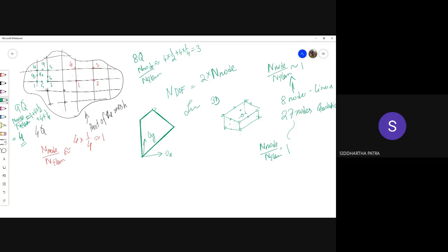Now for the mid side nodes, you see there are 1 2 3 4 5 6 7 8 9 10 11 12 sides, and each side will have one mid side node. Each side would be shared with 4 elements. So 12 times 1/4. Then there would be mid face nodes.